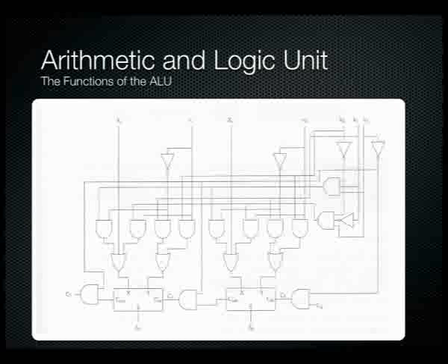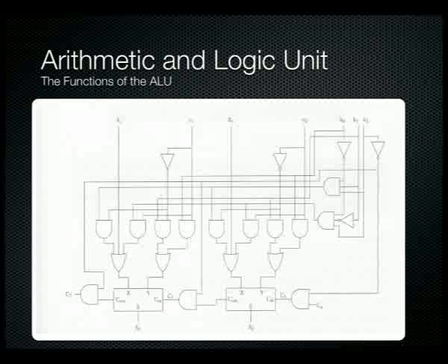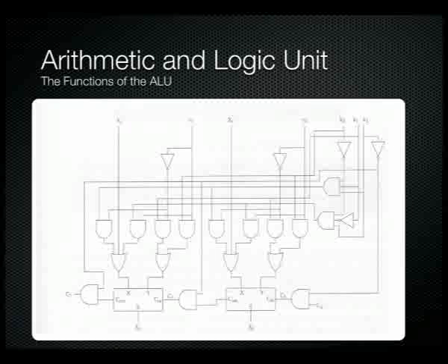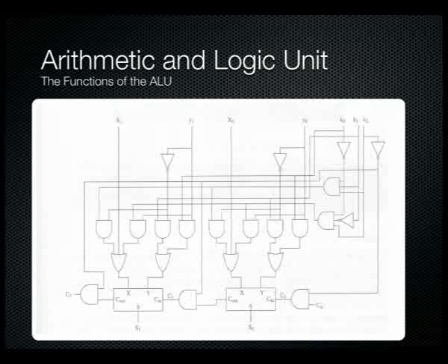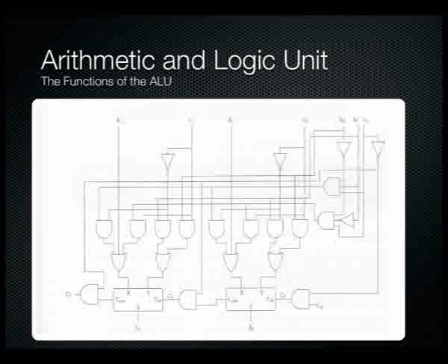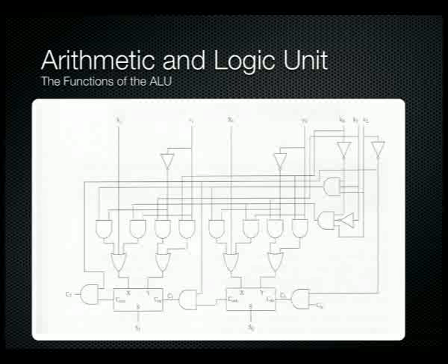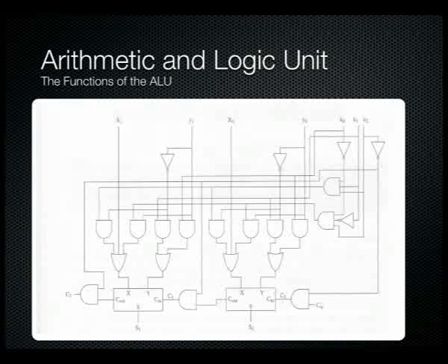So using a series of full adders, we can effectively create an arithmetic logic unit. So we've got these series of gates that sit around the full adders that allow us to implement a whole heap of different logical and numerical operations. So we can do additions and subtractions, we can do increments, we can do decrements, we can do lots of other wonderful things simply by driving the 3 control lines.